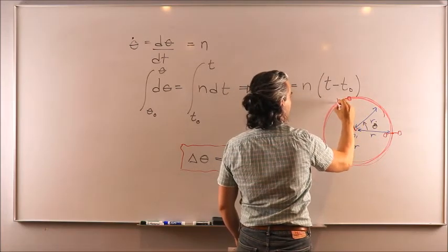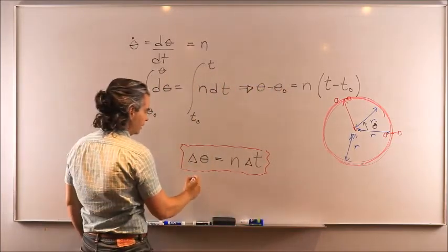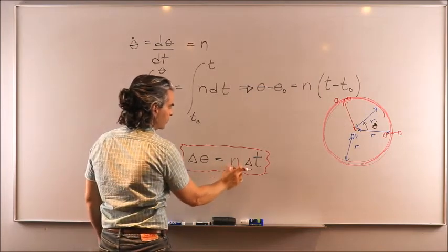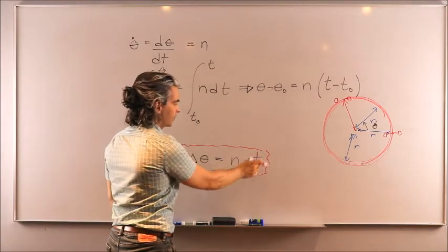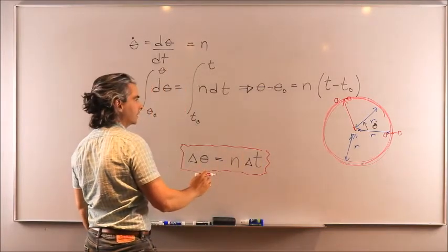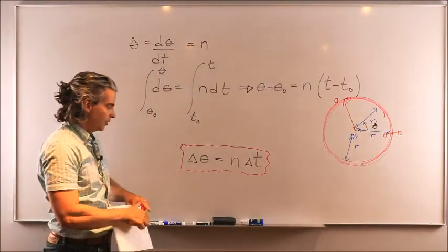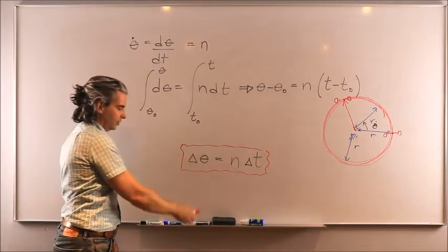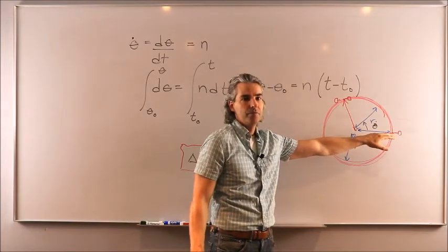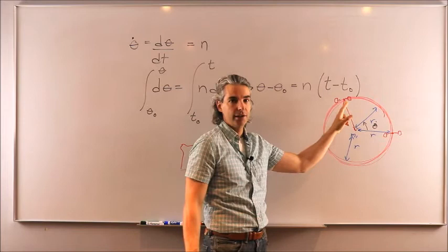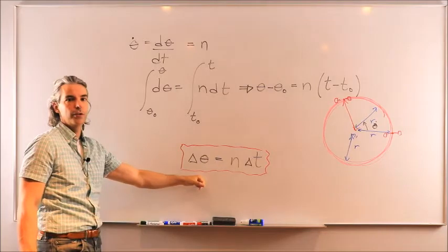here. While if you are orbiting along a circular orbit, this is very simple because all you have to do is say, okay, 100 degrees equal to the mean orbital rate, in that case, we have to put it in degrees per second, times what you're looking for, solve that equation, and then that would give you the time it takes to go from here to here. Okay? So that is the beauty of relating a true anomaly to time, because we can answer that question. How long does it take me to go from that initial angle to that final angle? Is it 10 seconds? Is it 10 minutes? Well, you just solve that very simple equation here.